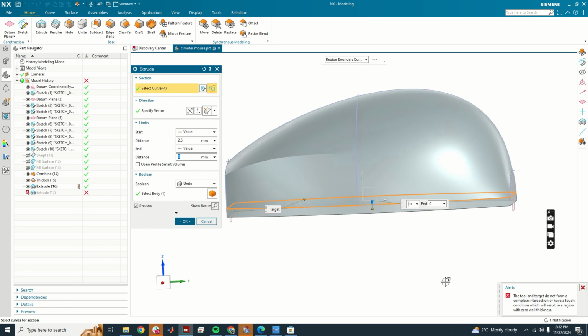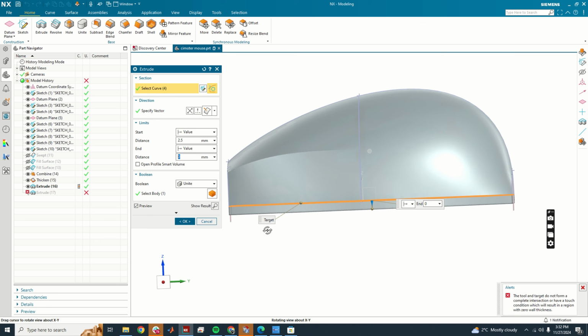Perhaps it's because, remember when we did that extrude cut? Maybe these two geometries are not actually intersecting. In fact, they're sharing a plane on the very bottom, so both planes are perfectly in line with each other. So maybe if I had it extrude upwards as well, at least a very small amount.